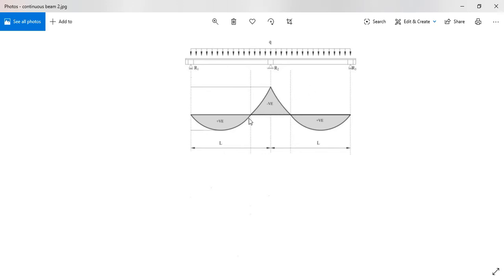But for the top, the maximum support moment is only at these intervals, so the rest will be just minimum reinforcement. 2Y16 would do, but whatever you design for your reinforcement to be able to carry the load, you design based on the moment that is there.